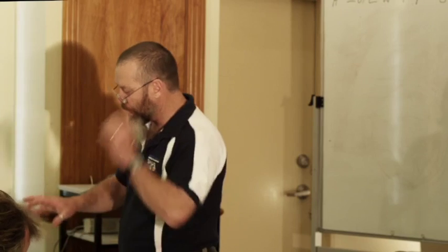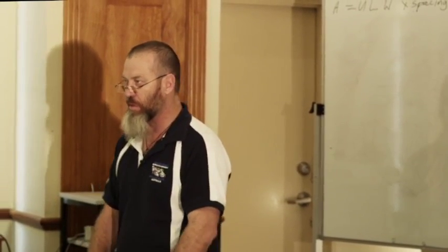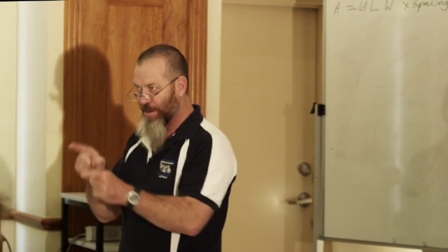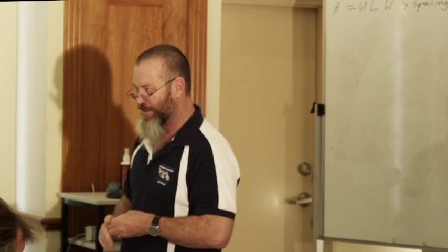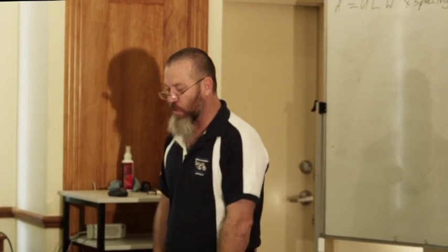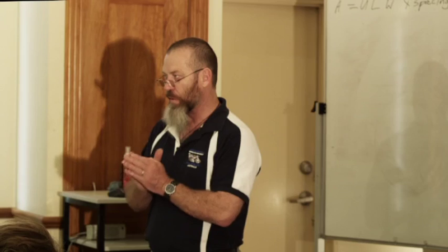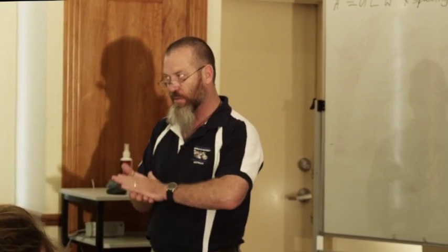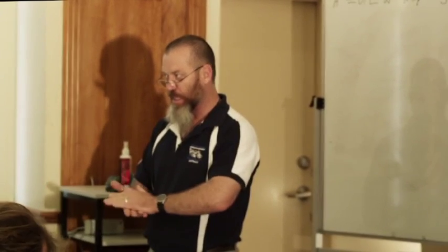Table 9.23, you don't have to worry about this connection or the next connection for your assignment. You do have to worry about ridge connections. Ridge connections come from table 9.24. Remember, we're looking for that. This is where you get your underpurlin tie-down connections. Now, don't get confused with this. This is tying your underpurlin down to your plates. It's not tying your rafter to your underpurlin, and that's why you're not using it in your assignment. Do you understand what I'm saying? You're tying your underpurlin down to your plates. That's where you go to get that connection.